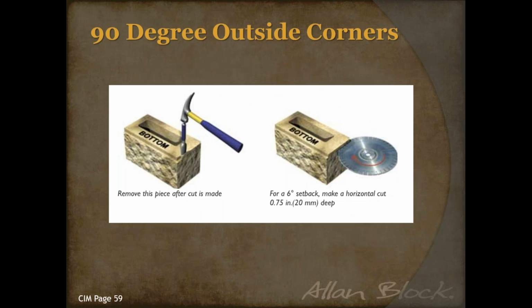I do want to put a little clarification out there with the corner blocks. Yes, it's got the lip on both sides, which makes it structurally strong, but the notch might have to be cut out in the field. Not all of our producers are this way, but you might have to cut that short notch. And there's a tech sheet on how to do that, and what depth it is.